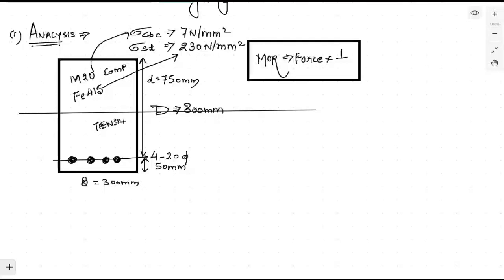While designing or analyzing the concrete beam, we have to consider that the tensile stresses are taken only by the steel. You have to ignore the tensile stresses handled by the concrete. It means that the concrete present below the neutral axis is of no use. The concrete present above the neutral axis will be fully utilized because the strength of concrete is maximum under compression. This is a simple concept.